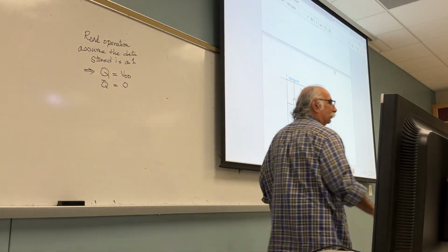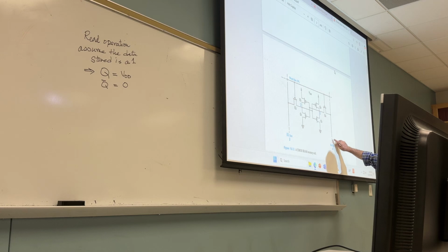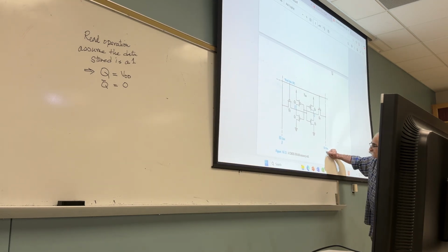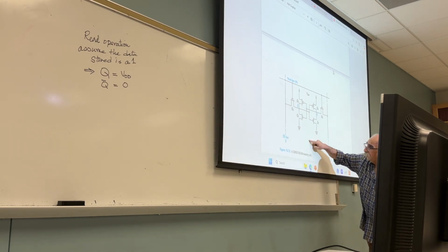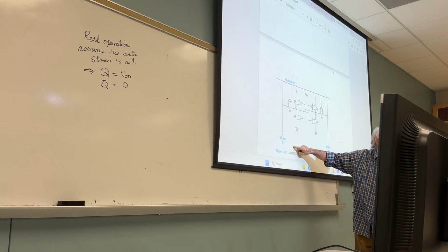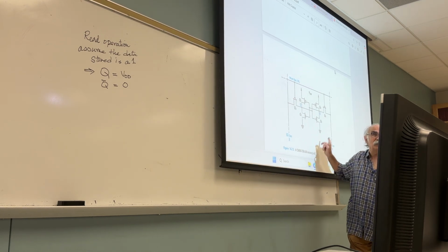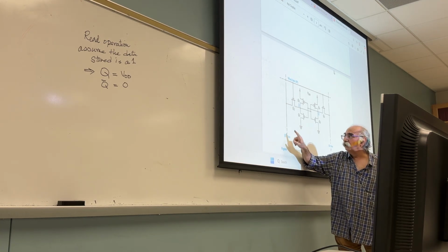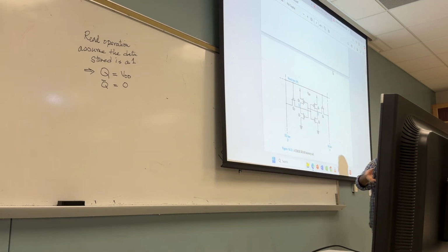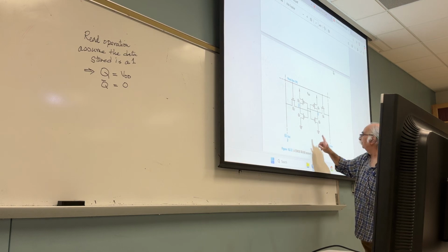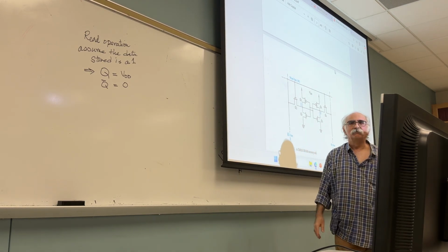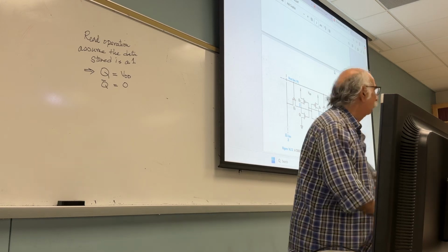Now before I continue, before I show you the steps, I need to make it clear to you. Between this bitline B and bitline bar, there is no inverter. Did you follow me or not? Yes. It's just a terminology, bitline and bitline bar. In other words, is it possible this one is VDD and this one is VDD? Yes, possible. There is no inverter between them. Can you write this in your notes? There is no inverter between the bitline and the bitline bar. Clear so far? Okay, let's continue.